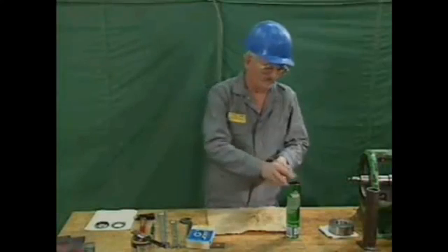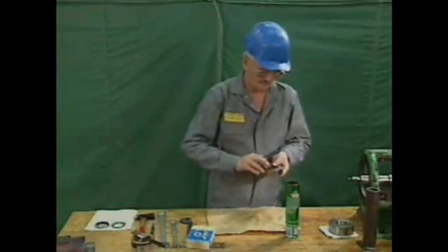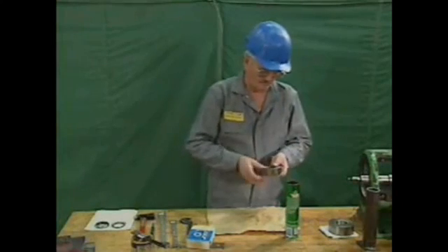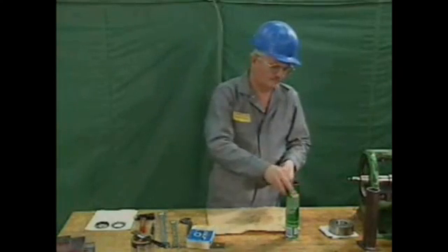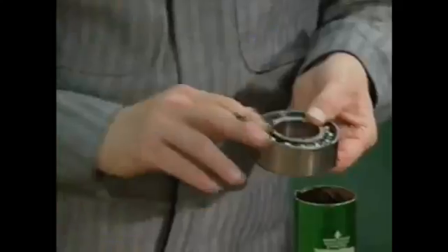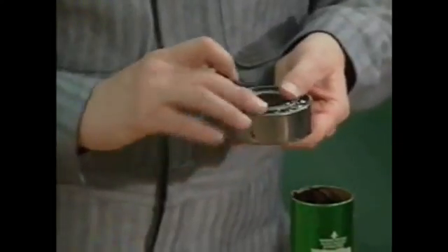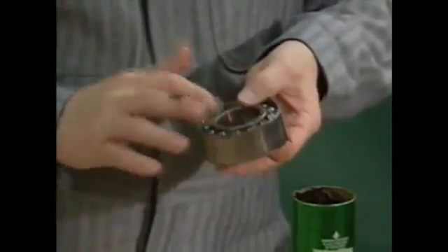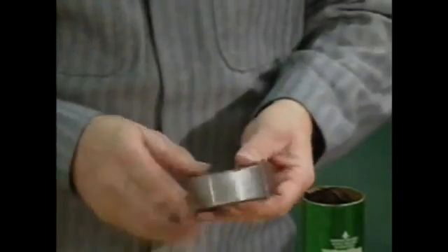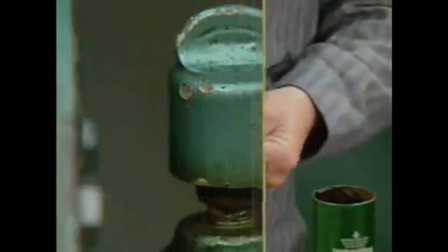When you're installing a bearing, you may have to hand pack the bearing with grease. To do this, hold the bearing in your hand while you press grease in between the rolling elements. Make sure that the grease is distributed evenly throughout the bearing. Pack the bearing 1/3 to 1/2 full of grease. If too much grease is added, rotate the bearing slowly to force out the excess grease.